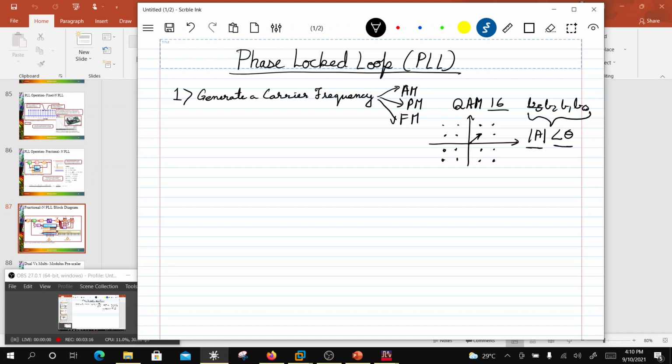And the second thing is, if this is a polar representation, so there is an amplitude and there is a phase, but this can also be represented as I and Q signals, right? So that means we have two quadrature signals, so there can be a rectangular component to this. There can be an I component and a Q component, so whichever you want to take, I and Q, doesn't really matter.